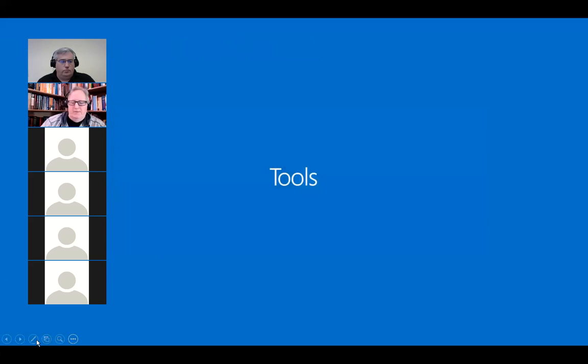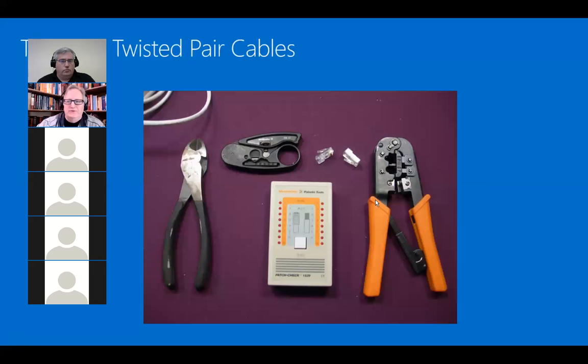I just wanted to add to that, Peter, and I apologize for interrupting the presentation, but you're absolutely right. A large pair, you've seen them at Home Depot, the large plier crimpers that you put on top of it, and it goes to what's called insulation displacement blades on the connector. The trick there, of course, is to have a short length on the wire ends, trim off the excess, do a clean punch, and not move them around a lot. I know a lot of people distribute your cables a lot. Those insulation displacement connectors are the first place you check if it's in a high traffic area where those cables might be run into.